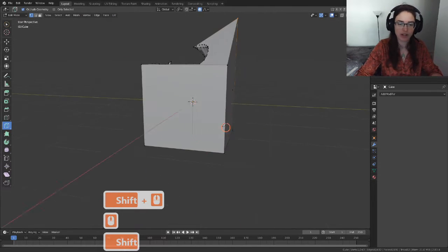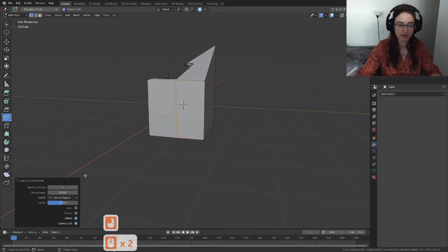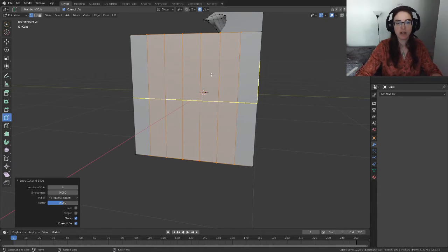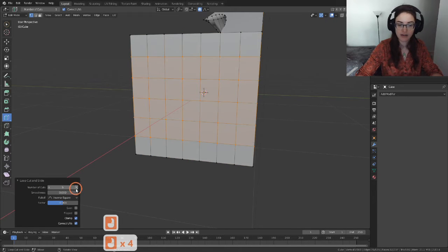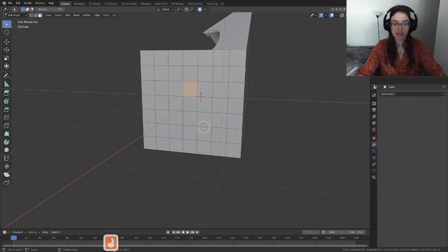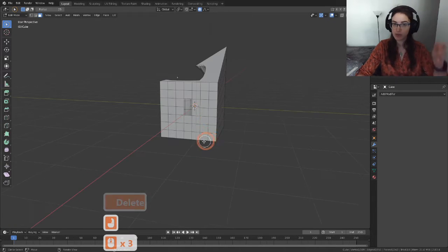And then one other quick thing, if you know you'll need a hole cut out, so if I was doing a window in a wall, you usually will want to plan ahead with your cuts and how many faces are there, so that you could just go in with face mode, do that selection and delete the faces individually, so that you can avoid doing a Boolean.